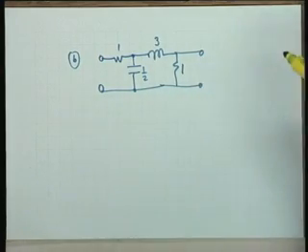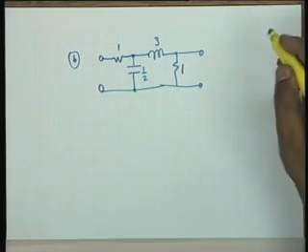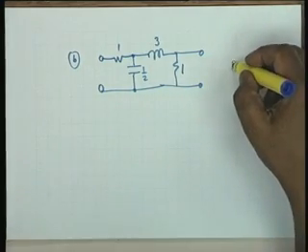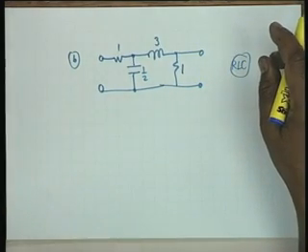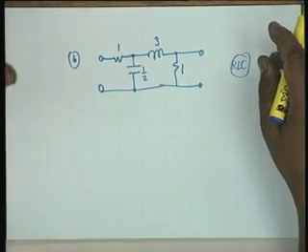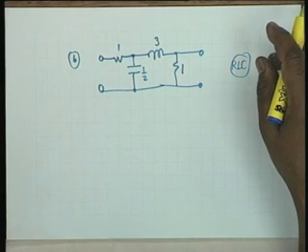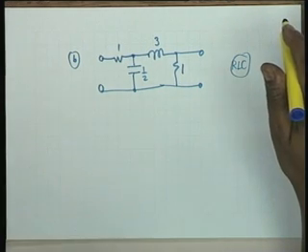But let me mention to you, it's not very important at this stage, that in an RLC network, if there are poles on the j omega axis, then residue conditions must be satisfied. Poles on the j omega axis, residue conditions have to be satisfied. This is not true for any other kind of pole.